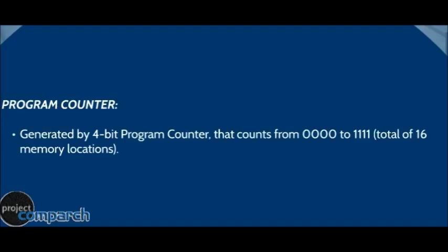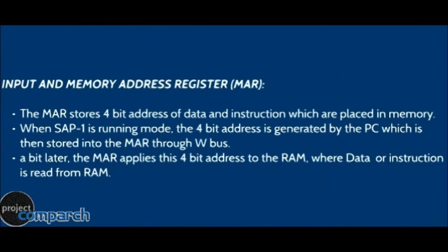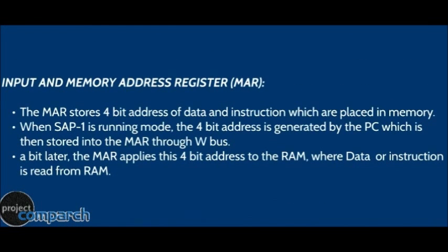Program counter. Generated by a 4-bit program counter that counts from 0000 to 1111, a total of 16 memory locations. Input and memory address register, or MAR. The MAR stores the 4-bit address of data and instructions which are placed in memory.